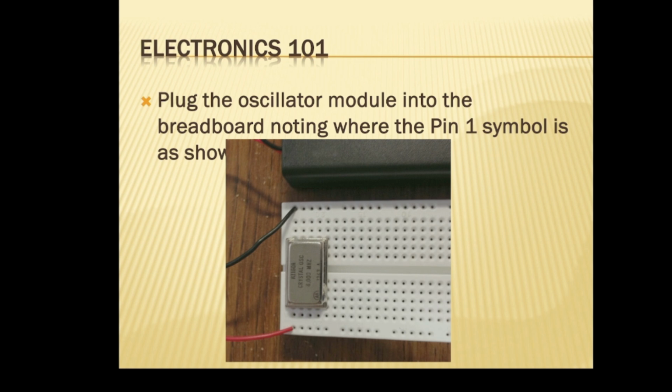Turn on the power yet? Not yet, not yet. Okay, and we're going to check it coming straight out. Okay, now turn her on. There it is. Okay, now we come out to here. Okay, you got the same problem. You got that 470K resistor. It's too big. It's all the signals getting sucked to ground with that capacitor on the outside. We need a smaller value there. Let me borrow your resistor.